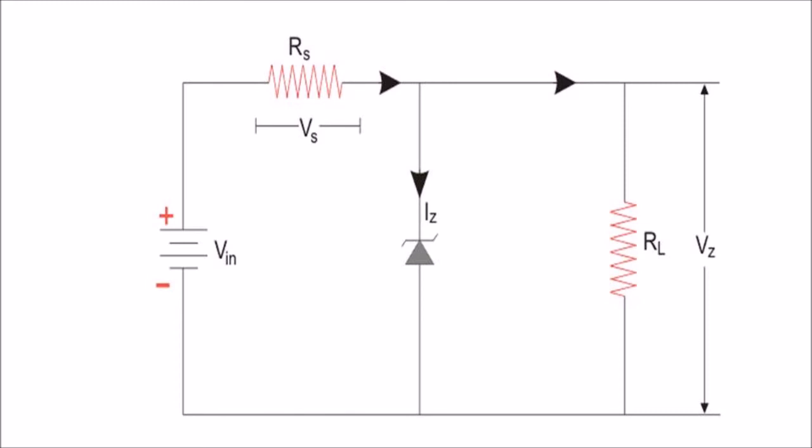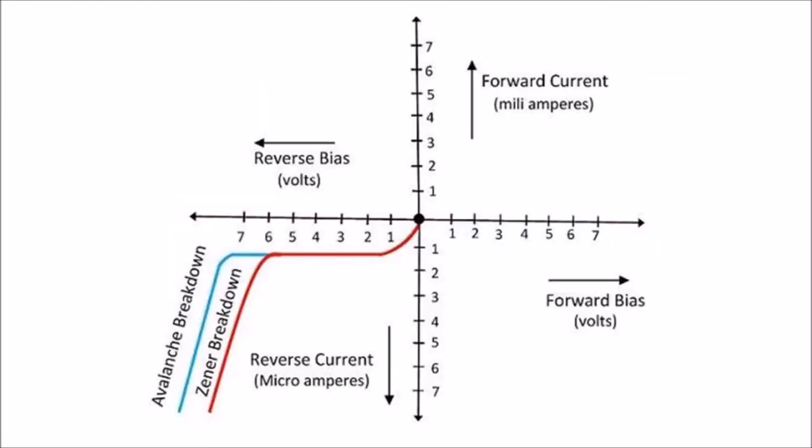So when it comes to the Zener breakdown, it is either due to the Zener breakdown effect that occurs below 5.5 volt or impact ionization that occurs above 5.5 volt. Both mechanisms result in the same behavior and do not require different circuitry. However, each mechanism has a different temperature coefficient.